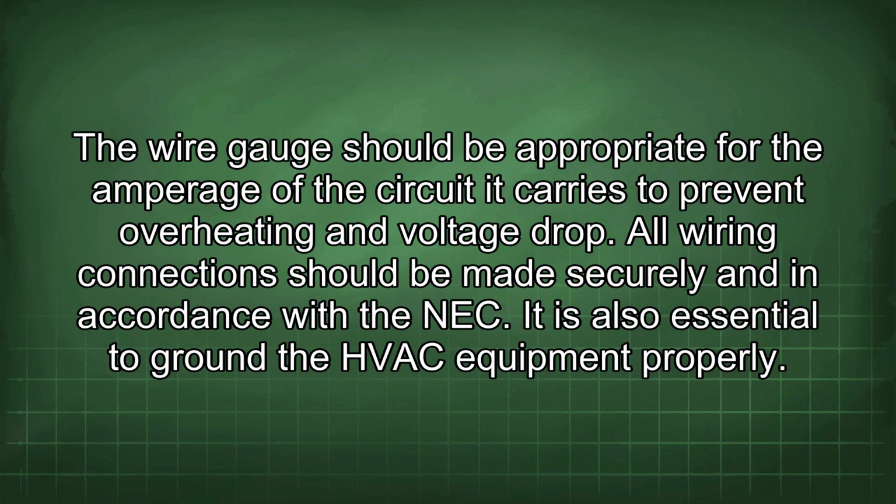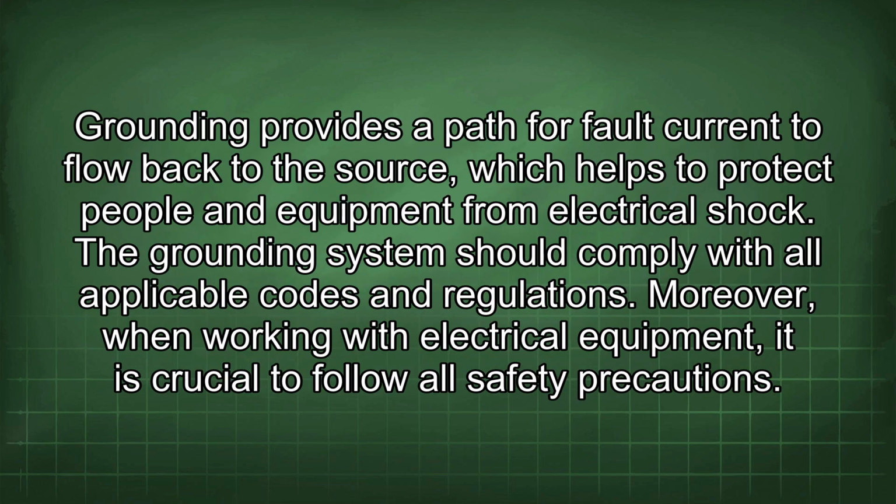It is also essential to ground the HVAC equipment properly. Grounding provides a path for fault current to flow back to the source, which helps to protect people and equipment from electrical shock. The grounding system should comply with all applicable codes and regulations.